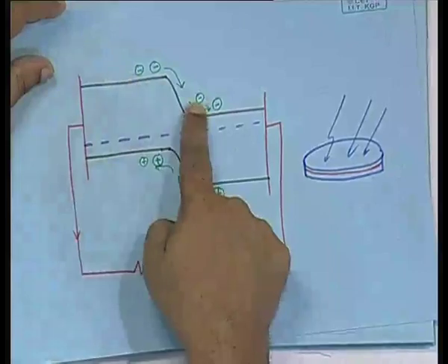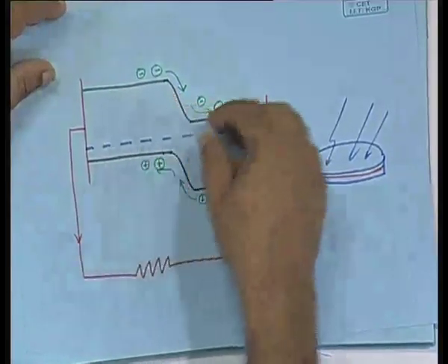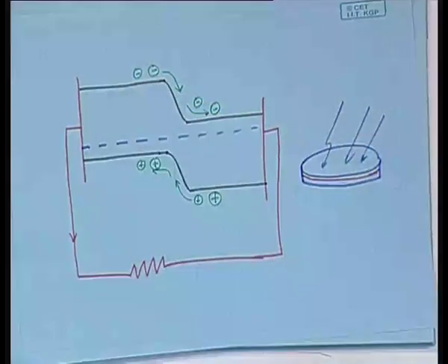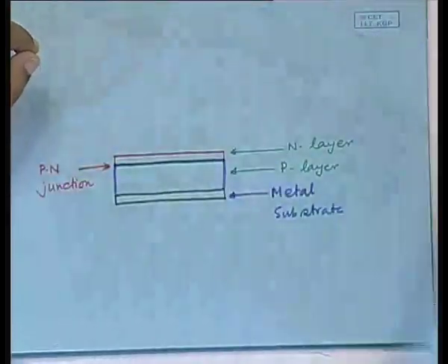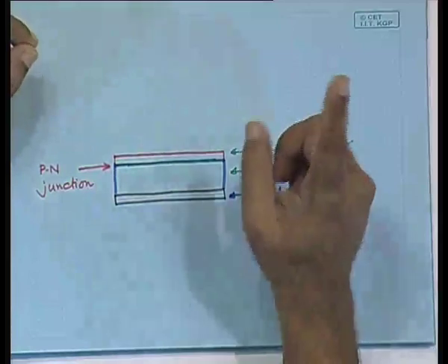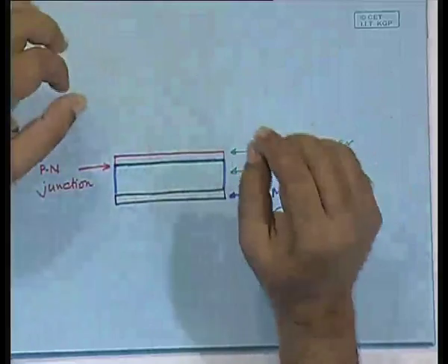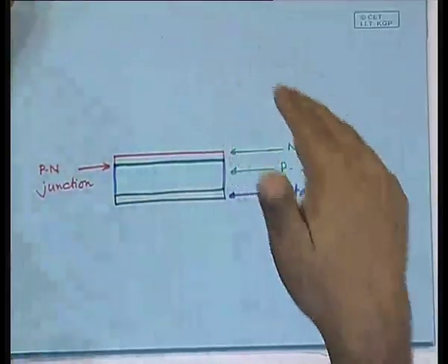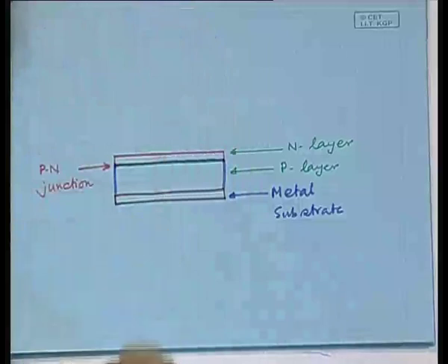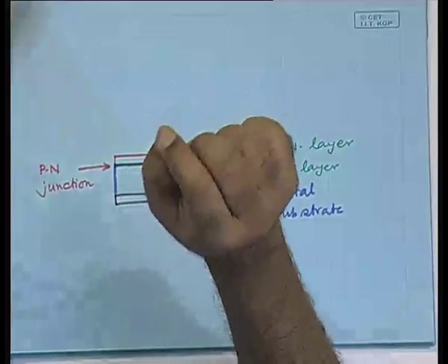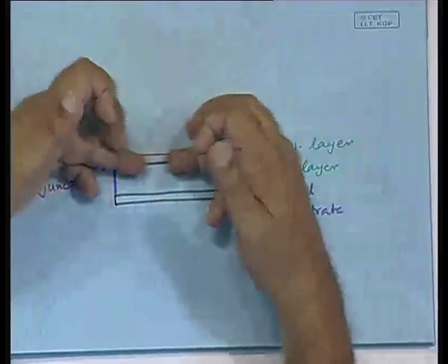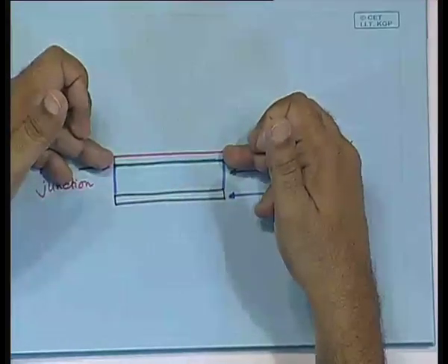Naturally the electron hole pair will be created somewhere here, not here. If that happens, then obviously the electron hole separation will not take place. So, in order for the electron hole separation to take place efficiently, the electron hole pair has to be created very close to the junction. For any material, you know the penetration depth. So, you have to make the arrangement in that chamber exactly, so that the p-n junction is produced only to that depth. That way you produce a layer of n.